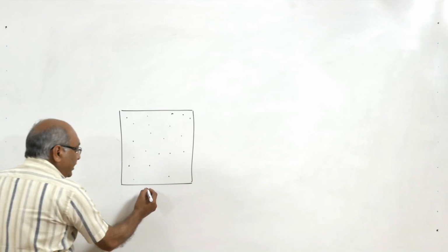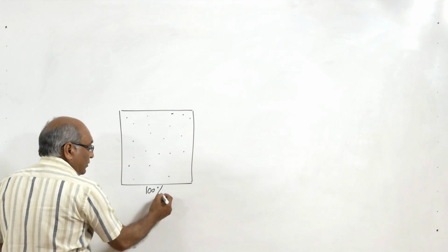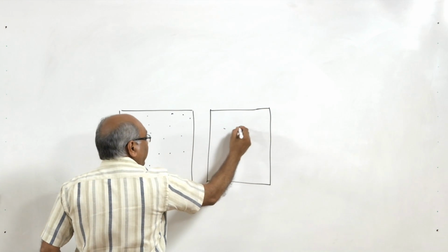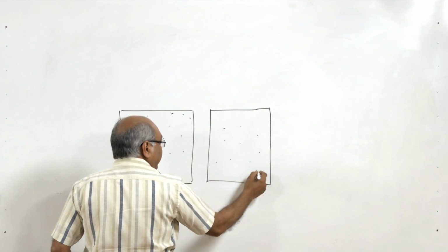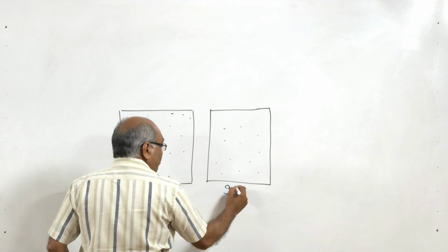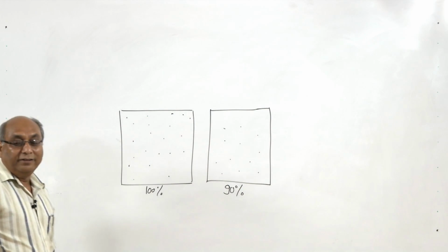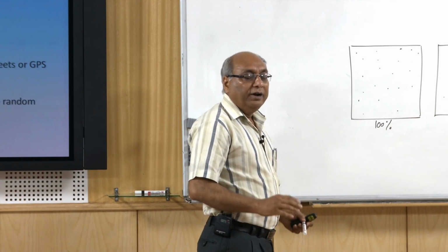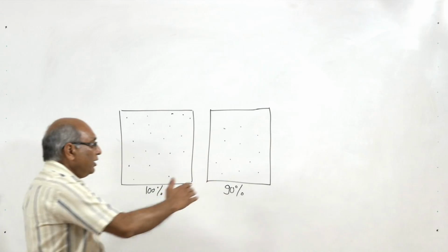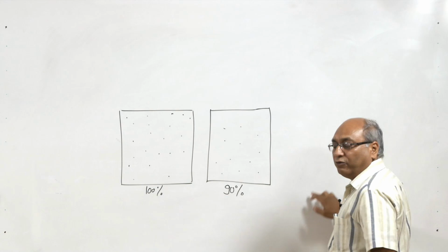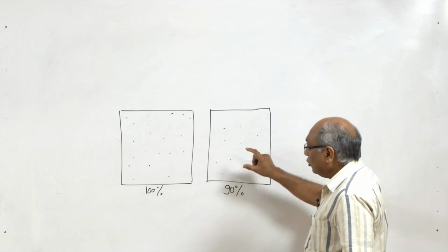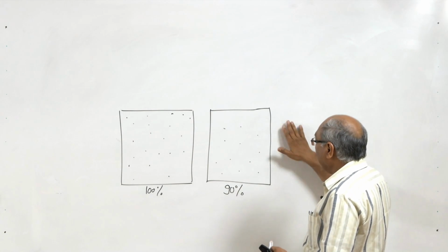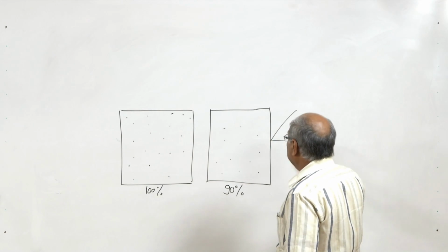So now say here we had the 100% data, and before interpolation we are now having 90% of the data. Randomly 10% data has been selected and removed temporarily from the original data set, and you then do interpolations employing 3-4 different interpolation techniques. So you will have different surfaces here, 1, 2, 3, 4 surfaces. Then use those 10% which you kept separately. Those points you use and compare with your different DEMs which you have generated.